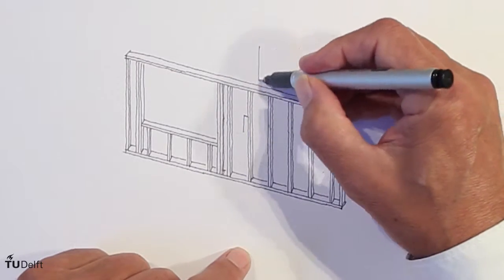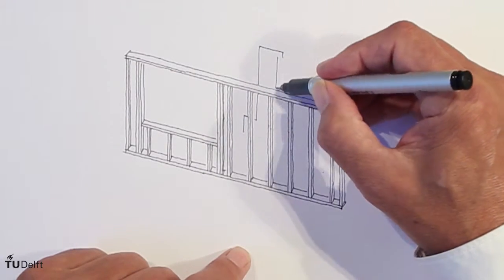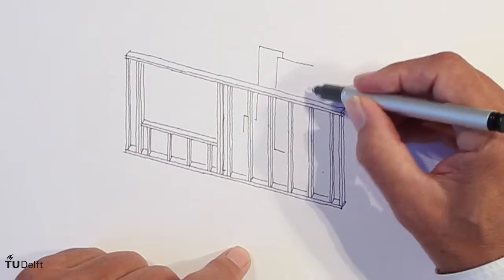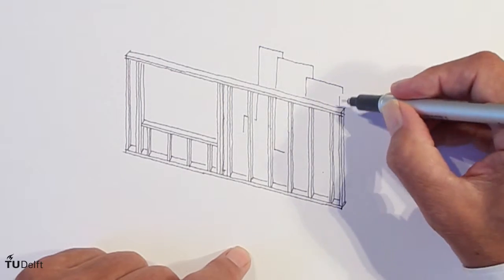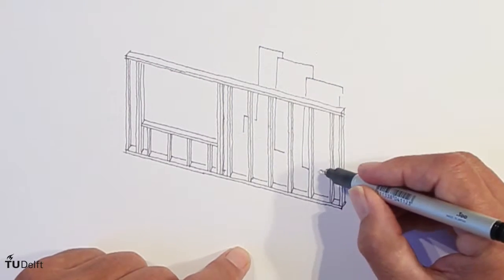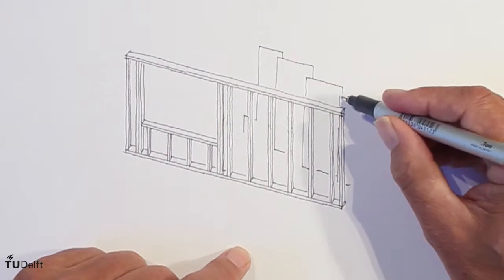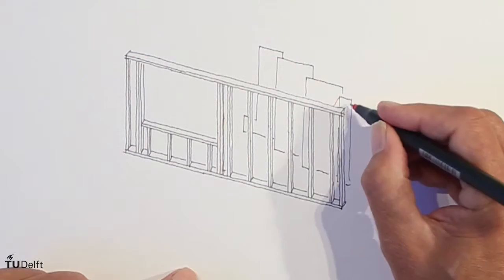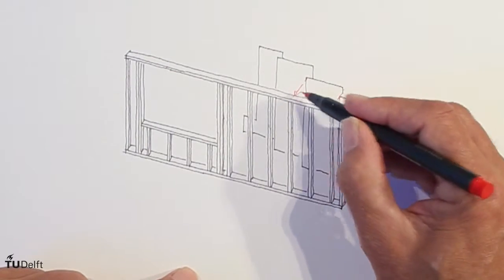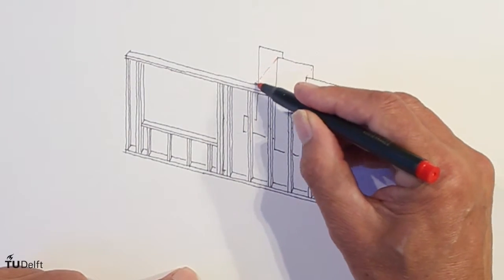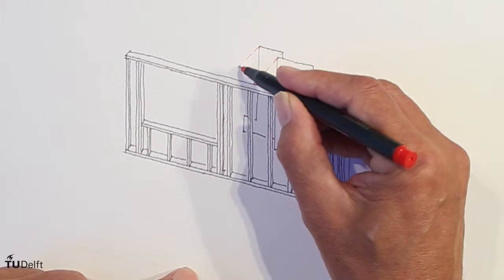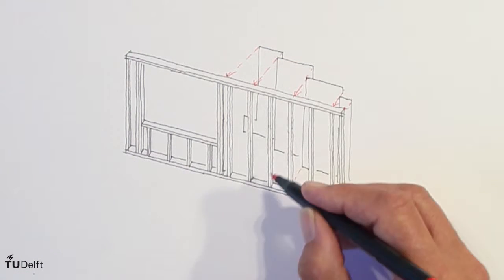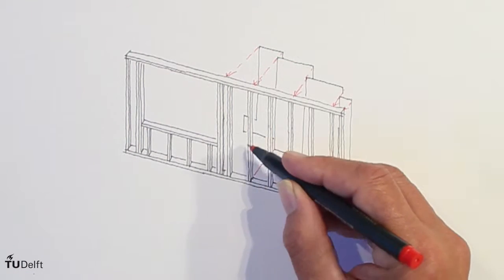The third type of inner layer consists of vertical posts or studs of wood or steel, covered on the inside or outside with a thin plate like plywood or chipboard. On the inward side, gypsum board is applied as fire protection and finish. At the bottom and top, the studs are connected with a horizontal beam. Studs, beams and plates form one structural element, made in a factory and transported as a whole.